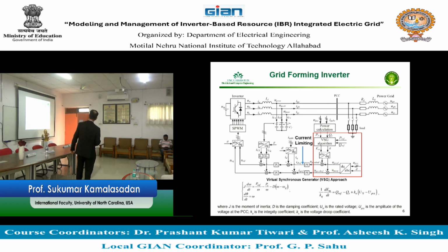So what this does is emulate some kind of an excitation system. Now we already talked about the excitation system in a generator, which comes from the flux, right? Mechanical power is converted into magnetic power, and from the magnetic power it is converted back into electrical power. That is a synchronous generator. What is there in the inverter? No flux. You don't have anything like a flux concept there. So how do you generate the voltage? Well, you generate the voltage from reactive power. And what is reactive power? It's the difference between the current waveform and the voltage waveform.